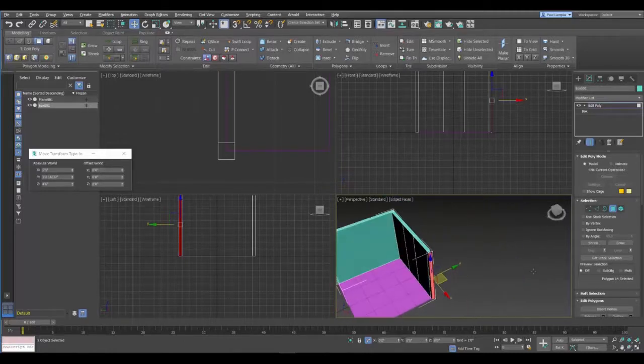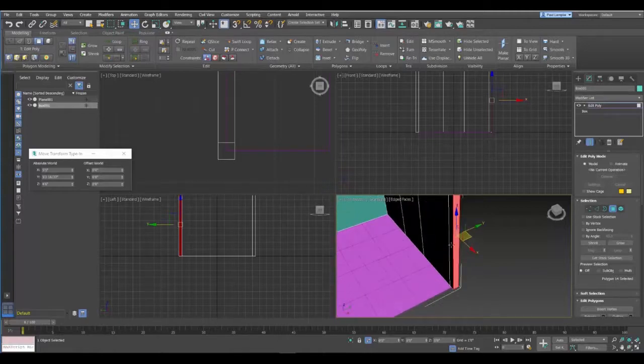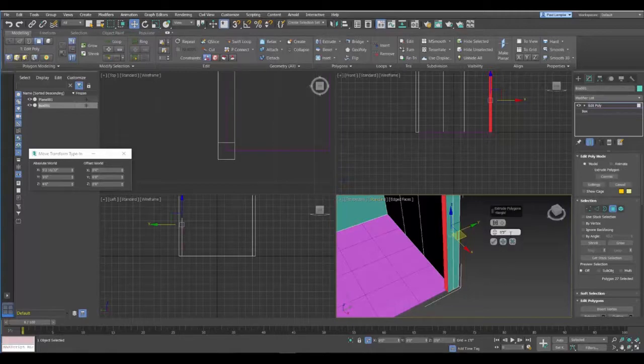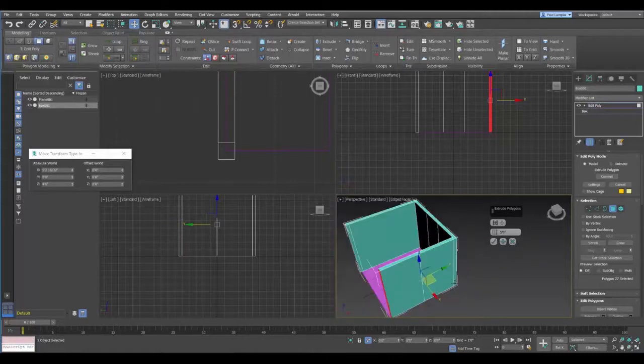Now I'm going to do a similar thing. I'm going to have a door over here. So selecting this, I'm again going to extrude. This is going to go 5 feet. And it put a second one in, completing the wall. But I'm going to change this to 30 inches, which is 2.5 feet. And when I click plus, it does another 2.5 feet, completing the wall.